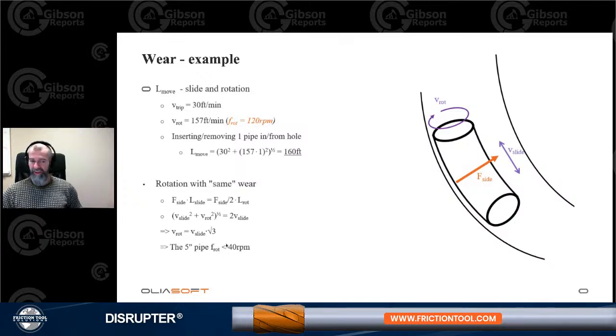But then you of course have to take into consideration that if you are reducing the rotation frequency, you are changing the torque and drag analysis, and then your side force changes. And then it's not that obvious that reducing the rotation frequency will give you less wear.